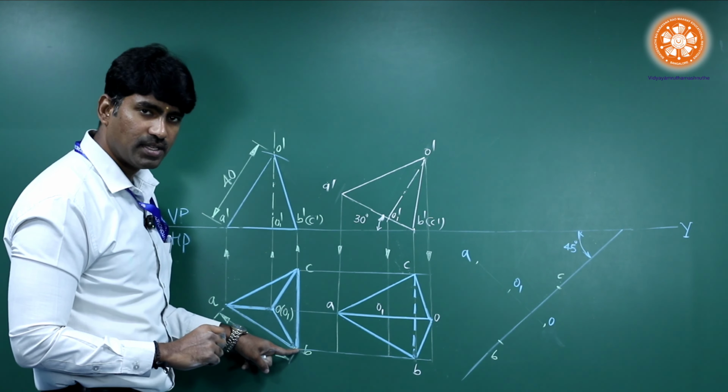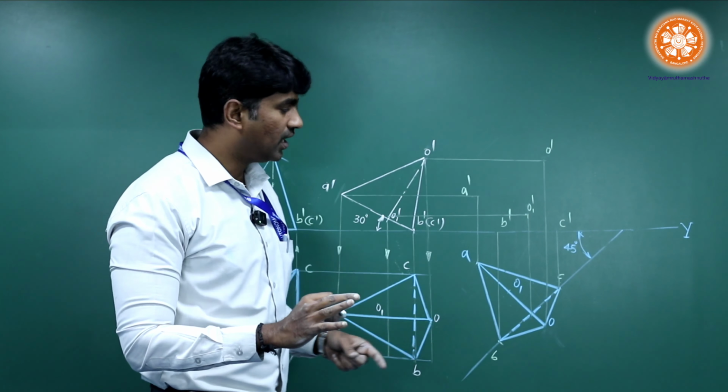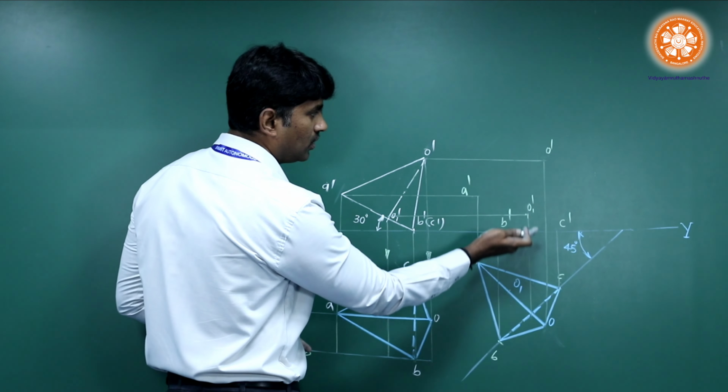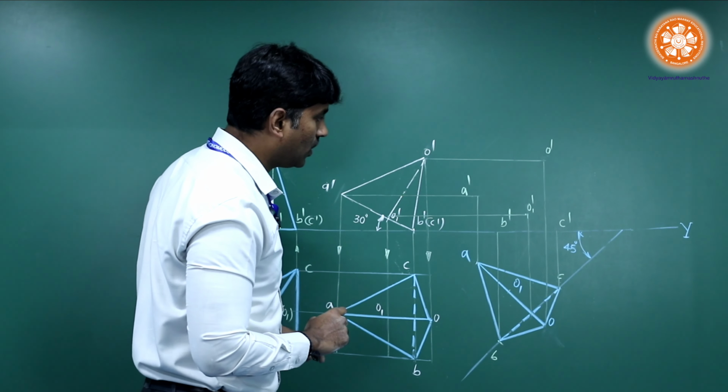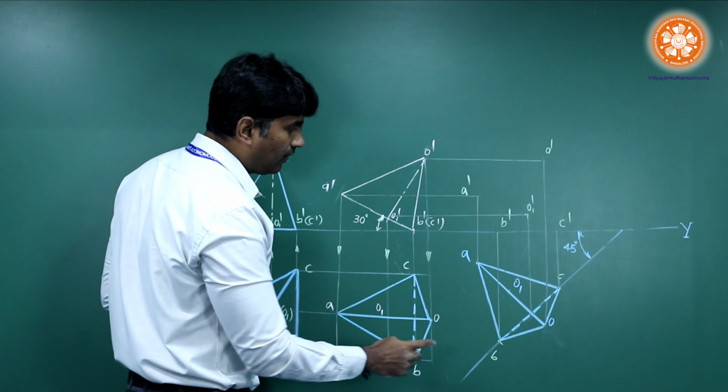Next, from this center, draw a perpendicular line, measure from this point to O, mark accordingly, again from this point to O1 and again A. After marking this, join this and make a replica of this figure somewhere here. After completing this position, what I have done is I have just projected from this to the upside and this to the right side just to get the final position. So here, after projecting, I have met the points A dash, B dash and the points accordingly.